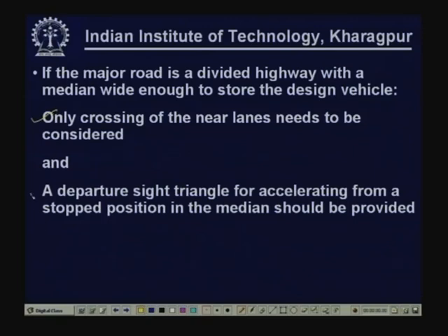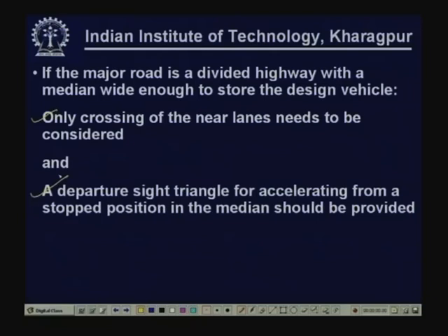Therefore, a departure side triangle for accelerating from a stopped position in the median should be provided, because the vehicle may stop in the median. So, from stopped position, obviously it will be a case for departure side triangle. So, a departure side triangle for accelerating from a stopped position in the median should be provided.